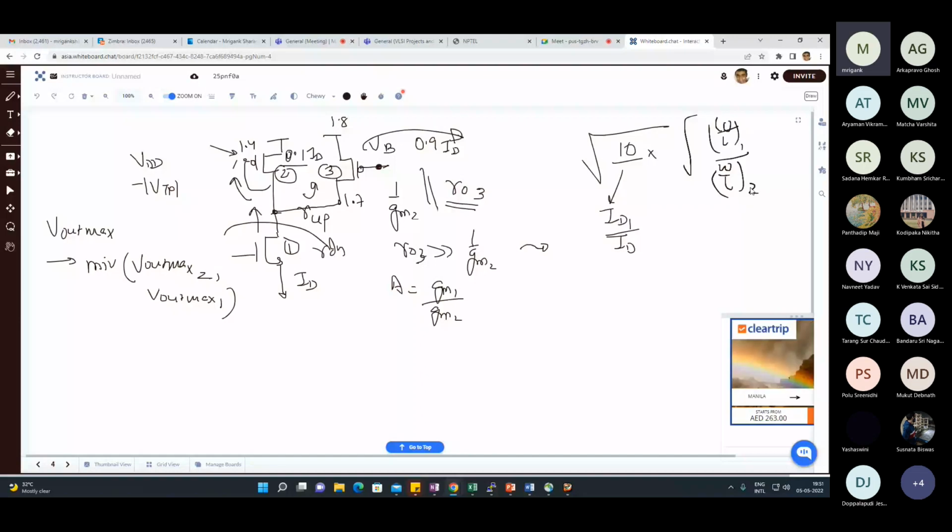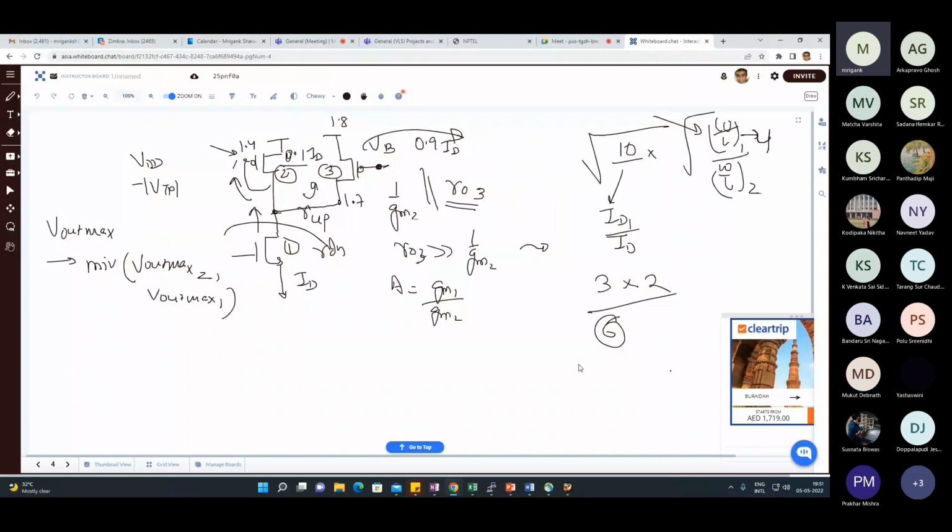So that will basically reduce the pressure on this W by L ratio. So earlier, now this is going to give you something higher than 3 already. And then if you want another factor, maybe if you get 4 times, you will get 2. So a gain of 6 coming just by keeping this factor of 4. Whereas in the earlier case, if you had to get 6, you need 36, right? That is the advantage. So with this circuit, we can basically get higher gain while reducing the sizing constraint.